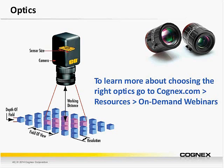The right combination of lens and extension tube will acquire the best possible image. A fixed lens is generally part of a fully integrated smart camera. Fixed lenses typically use autofocus. This could be a mechanically adjusting lens or even a liquid lens, and it will automatically focus on the part. Autofocus lenses usually have a fixed field of view at a given distance.